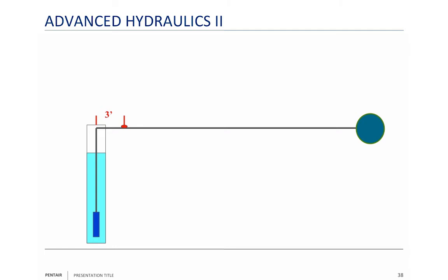So instead of just saying you've got a cavitation problem, I said to him, what's your flow rate? He says 60 gallons a minute. I'm thinking, 60 gallons a minute with a 70-gallon-a-minute pump? No, that's not cavitation. Unless, what's your pipe size? He says 2-inch. Now all I have to do is go to my friction loss chart.